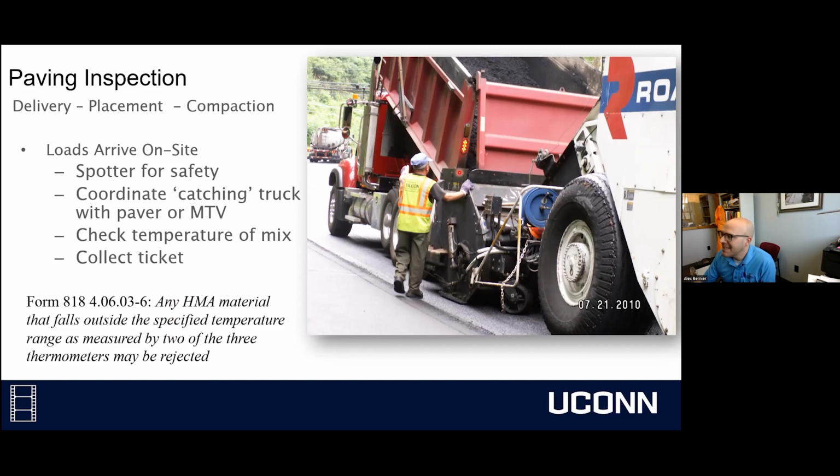We're going to have someone standing by either our material transfer vehicle or paver hopper, and they are going to be our spotter, making sure the trucks can safely back in to discharge their loads. They coordinate catching the truck with that hopper.